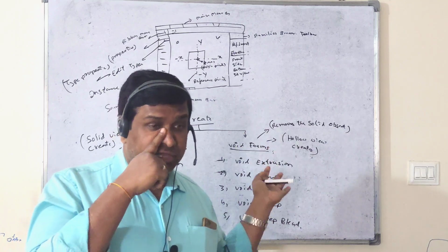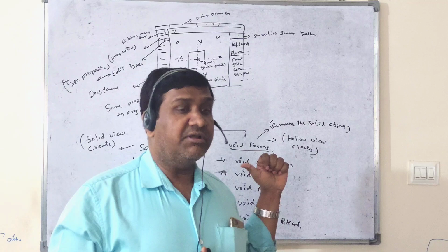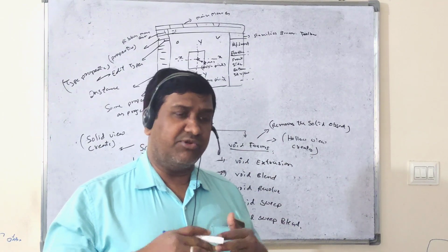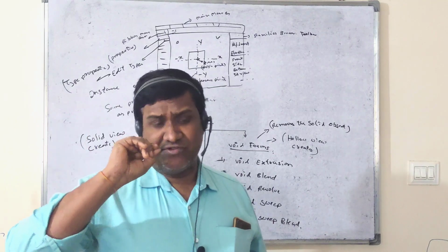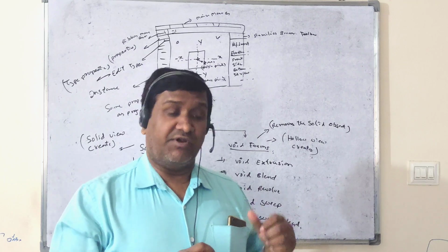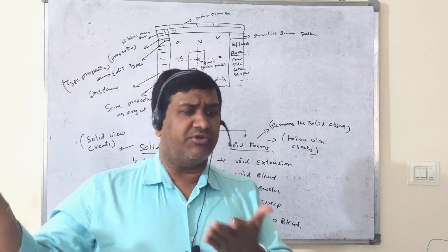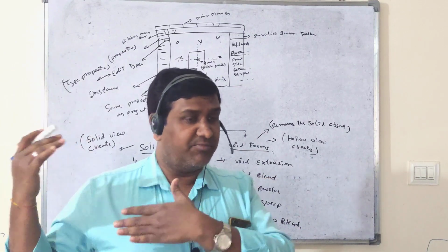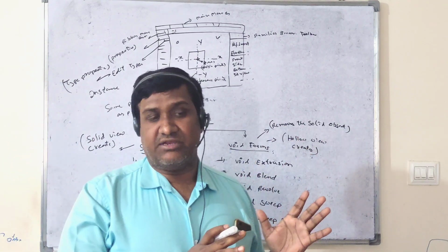So which tool is going to be utilized for creating these objects? We have to work with extrusion, blend, these tools. With the help of this we can create that object as per the size, as per the dimension view, as per the originality of that project's properties. Everything is going to be worked out with these tools only. Some companies will also provide AutoCAD files, with top view, front view and side view. By seeing those views, we have to create the solid object here.